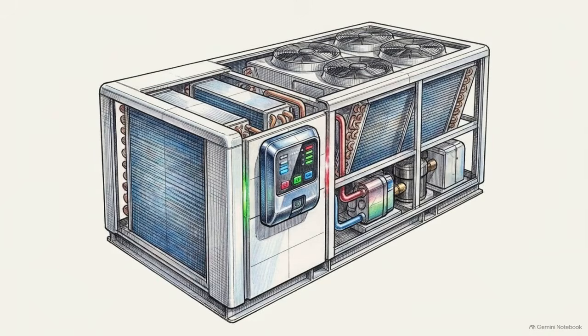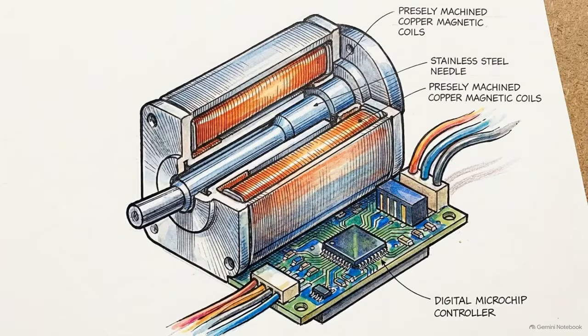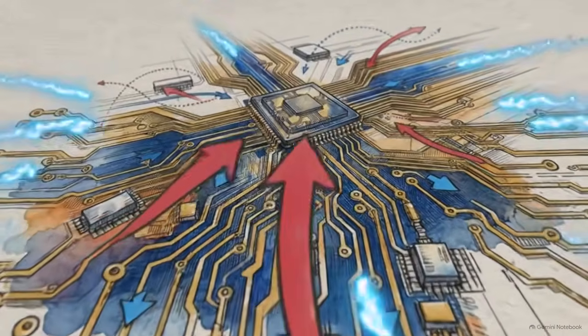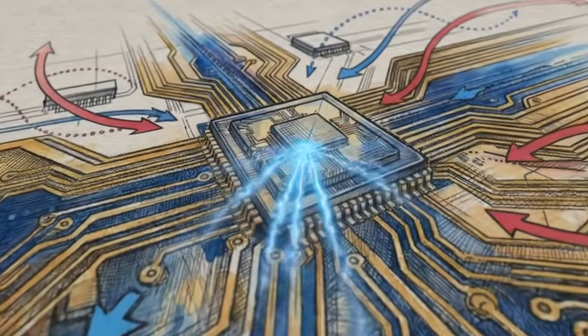As systems scale in size and demand greater efficiency, modern variable refrigerant flow installations utilize the electronic expansion valve, or EEV. The EEV replaces the mechanical diaphragm and bulb with electronic thermistors, a digital controller, and a high-precision stepper motor to dictate the exact position of the needle. Meeting the demands for wider operating ranges and extreme energy efficiency requires mass flow control to evolve from mechanical-pneumatic balance